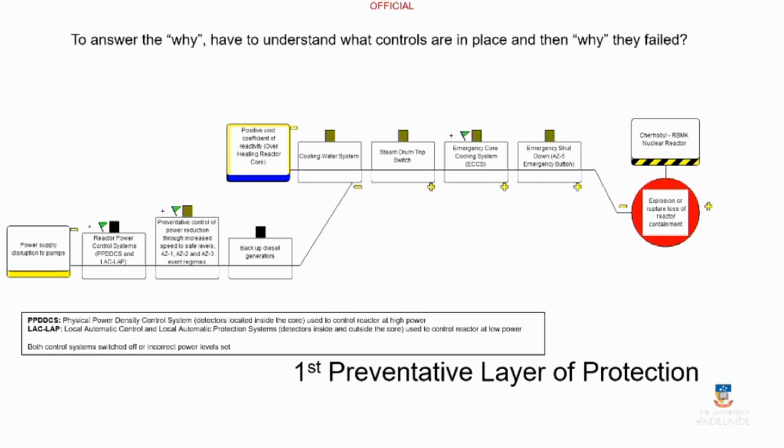But this system had never been tested, even after the design, even against Russia's own nuclear regulations. Before you commission a reactor, you've got to do critical function tests on all your critical controls, and this was one of them. So they started the reactor, they were producing power for a number of years, but they still had to tick the box that this backup power through the winding down of the turbines still works. And this was the test they were trying to do on that fateful evening.